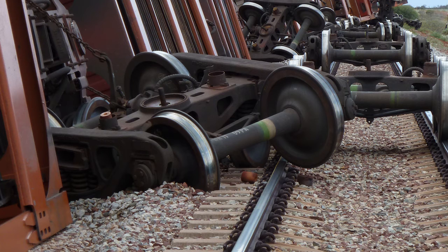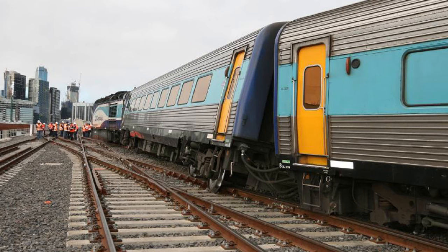Because brakes can't now be applied to the rear half of the train, the momentum of the rear half will still be pushing the front half forward. This can cause the train to derail or overshoot into a section with an oncoming train, causing a major accident because the train couldn't brake correctly.